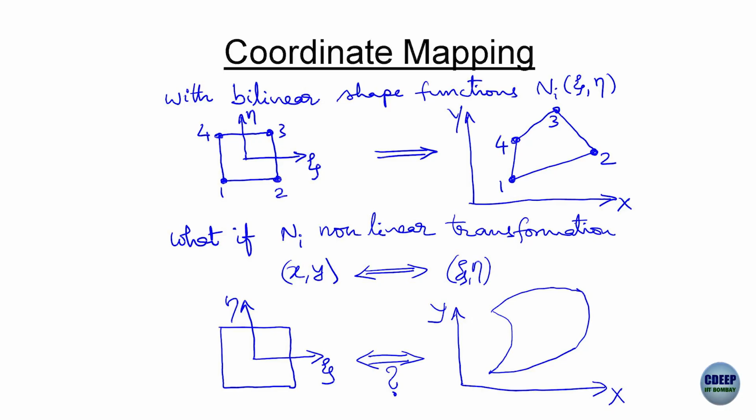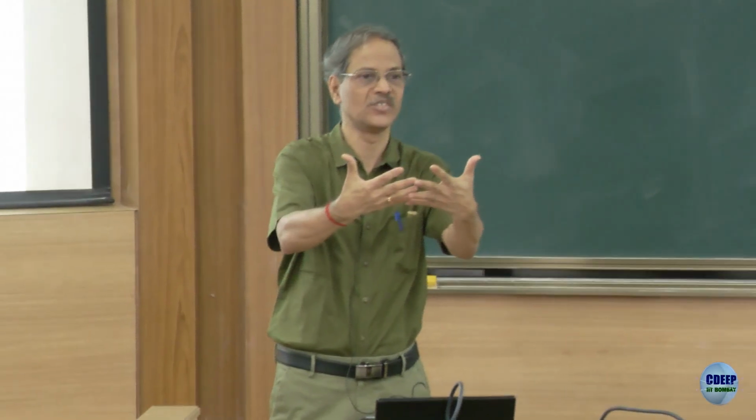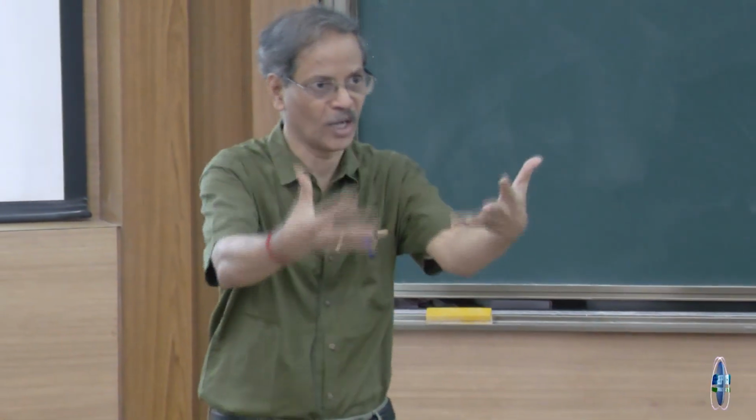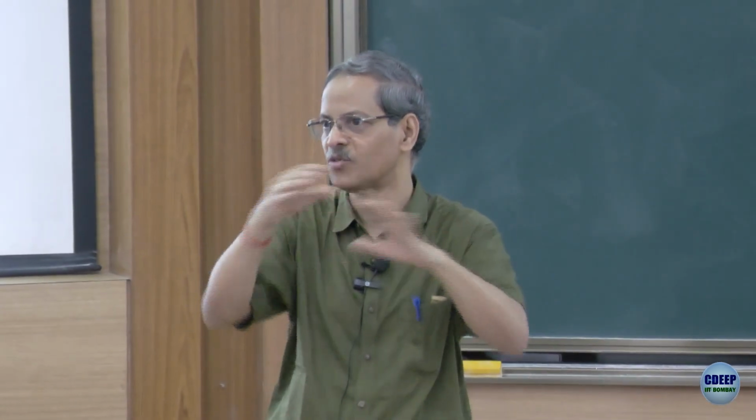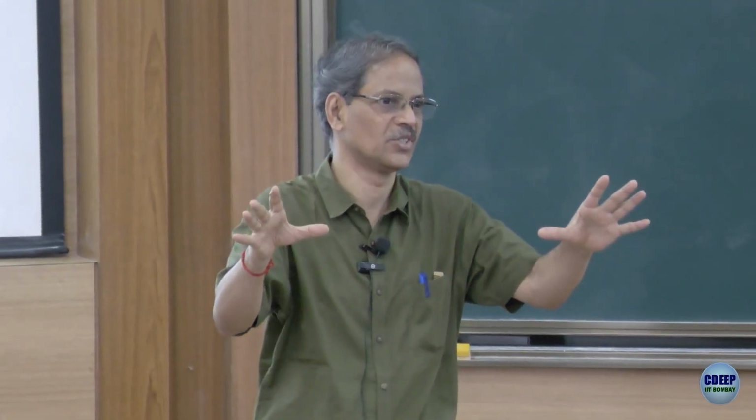That is the stage we were in the previous class, in order to be able to model curved geometries in the real physical world. In the mathematical world of formulating the element, doing the integrals and all that, it would still be zeta eta, it would still be that perfect square, -1 to 1. I am going to distort it to represent a curved element. So, what you would see in the mesh in the software that you are going to use for your course project, in the screen you may see a distorted geometry that you are modeling with fillet radii, curves, holes, whatever features.